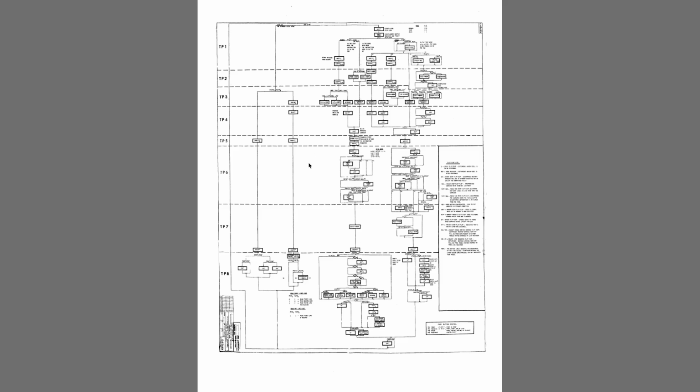In cycle 0, the machine is reading an instruction from memory mostly, and in cycle 1 that instruction is executed. So each cycle also corresponds to one complete memory cycle, meaning read and write. Now with that in mind, we can understand the instruction set of the TX-0.